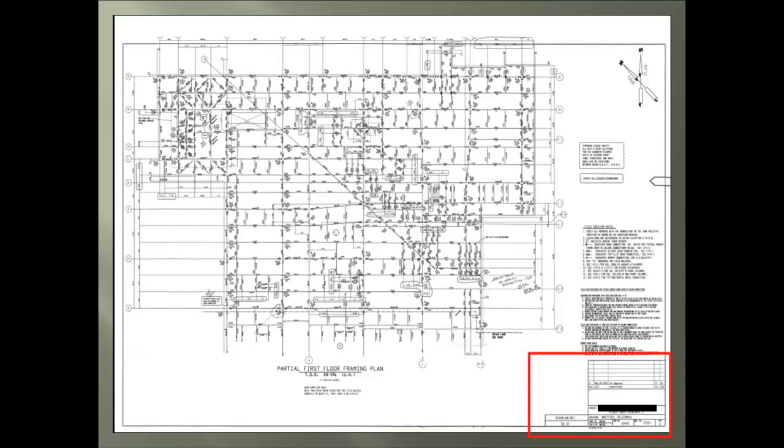Here we see the project and sheet information box. The first arrow shows the box for the latest revision or change order number and the date of their approval. With the second arrow, we find a box for the subcontractor's information that these shop drawings are for. Here is the project information box, plus notice the job and sheet number for these shop drawings.